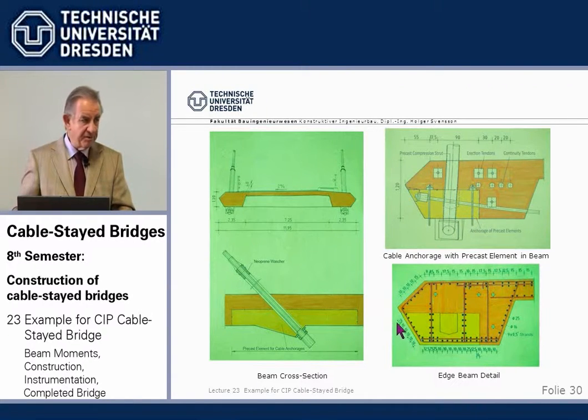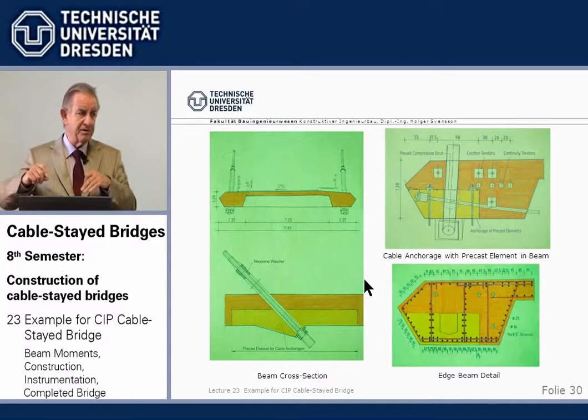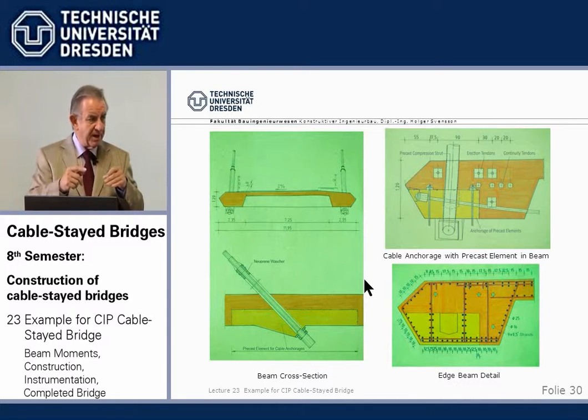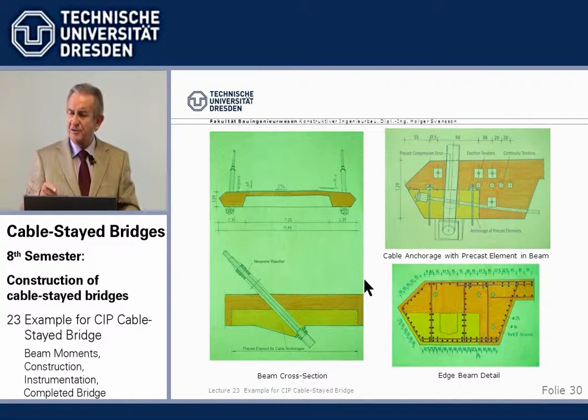And the purpose for that is we wanted to use the final cables also during construction as support of the 12-meter long traveler during casting. We didn't want to use auxiliary tiebacks, which had to be elongated and all that. I explained that to you earlier. So here we found a way, for the first time, to use the permanent cables.